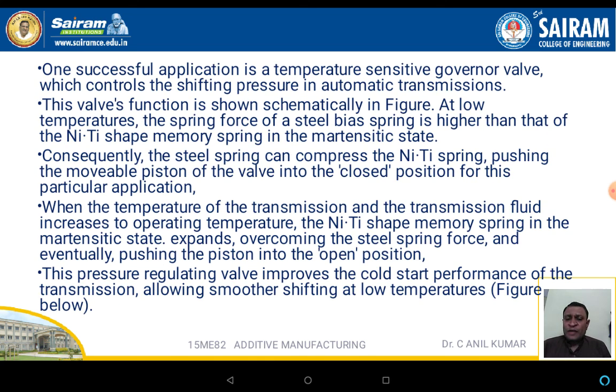One successful application is the temperature-sensitive governing valve, which controls the shifting pressure in automatic transmission. Consequently, the steel spring can be compressed by the nitinol spring, pushing the movable piston of the valve into a closed position for this particular application.